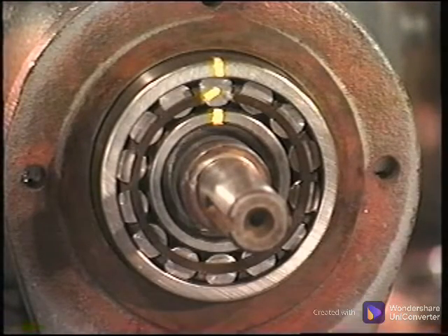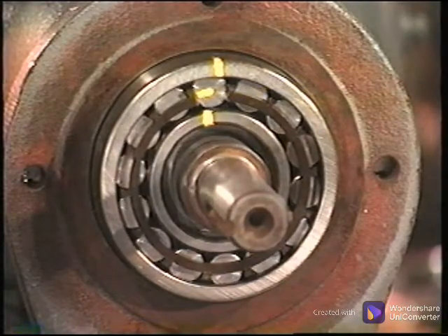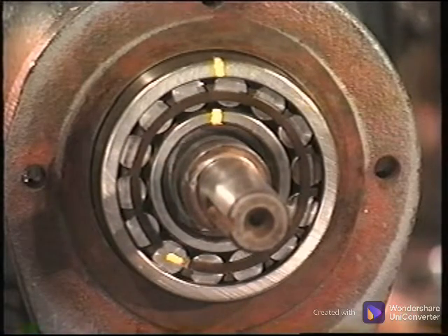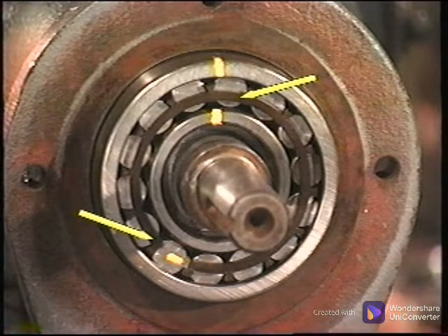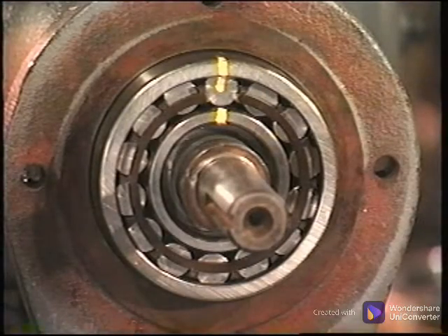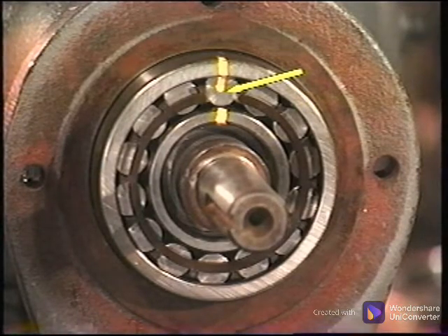After lining up our reference marks, the cage frequency can also be approximated by rotating the shaft one full turn. With one complete revolution, we see that the cage went less than halfway around. Cage frequencies usually occur between 0.3 and 0.47 times the shaft turning speed. A defect on a roller will also generate certain discrete frequencies, depending on how many times the roller turns over during one revolution of the shaft. With the reference marks in line again, we rotate the shaft one full turn and this time count the revolutions of the roller.